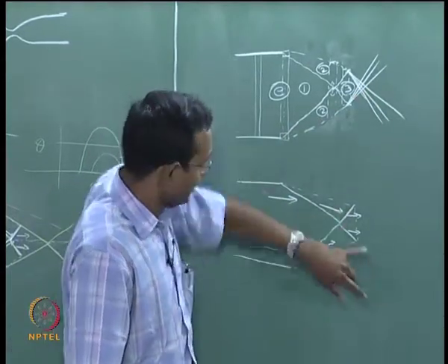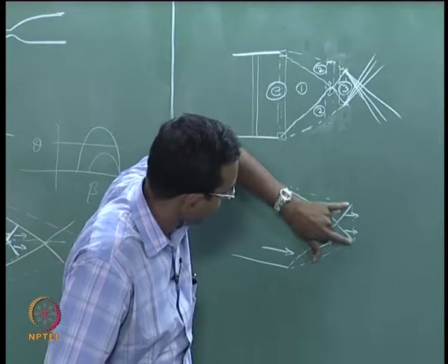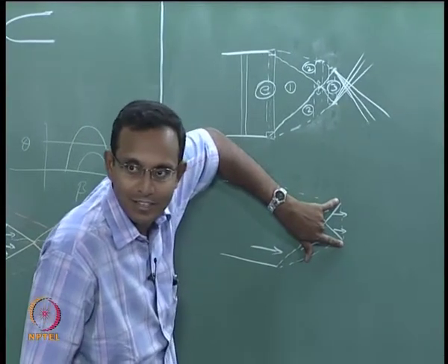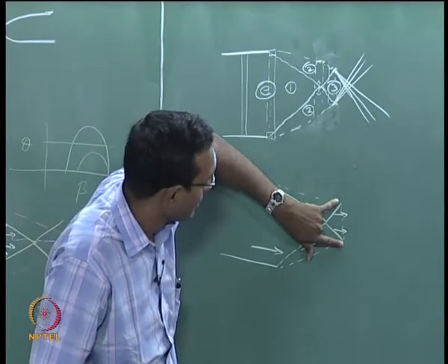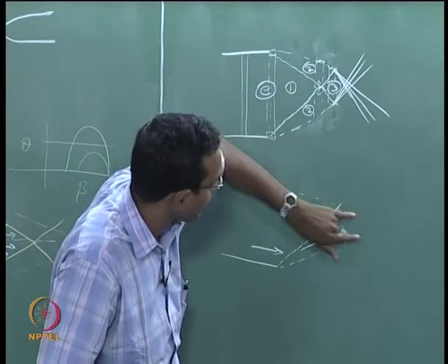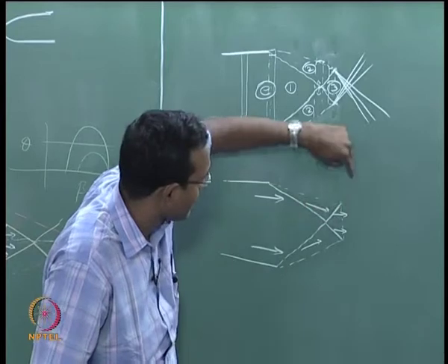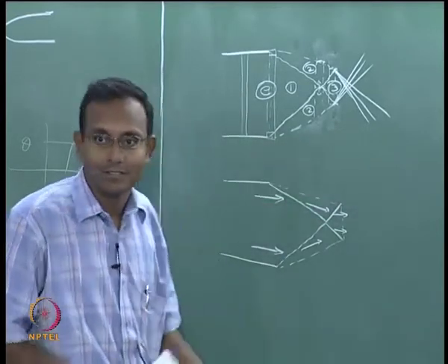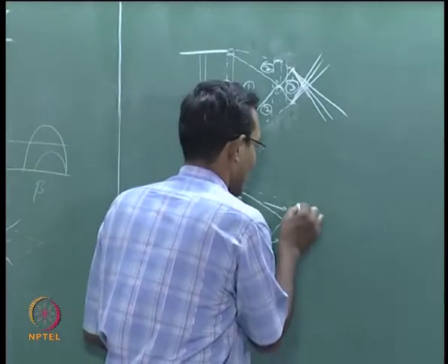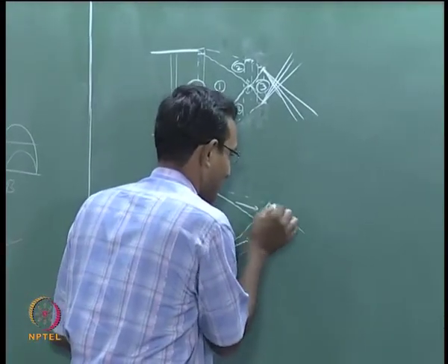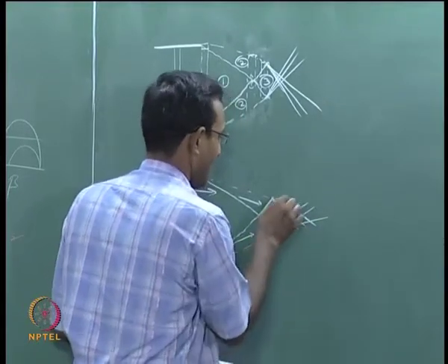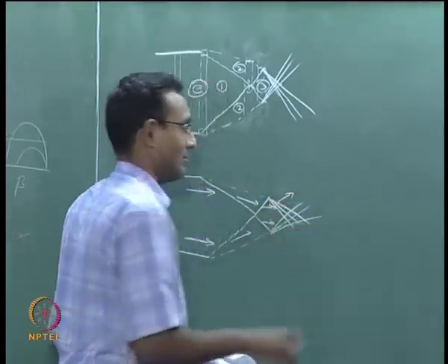The other way of looking at it is, it has got compressed and now I have a new jet going out like this, as if it is a shrunk jet coming out, and when that jet comes out, immediately it is seeing that the pressure here is higher than the outside pressure. What should it do? It has to expand. So there will be expansion fans here, and the fluid element goes out.